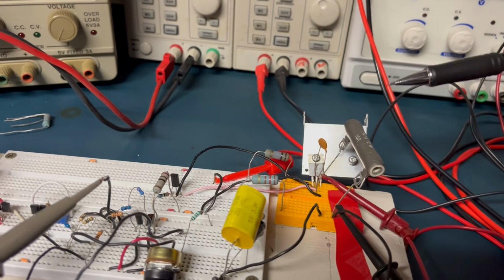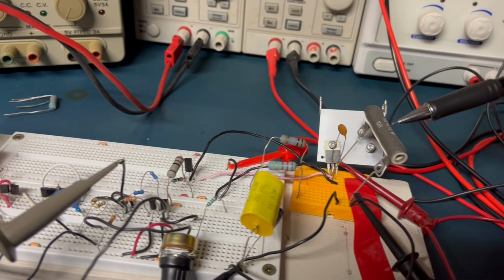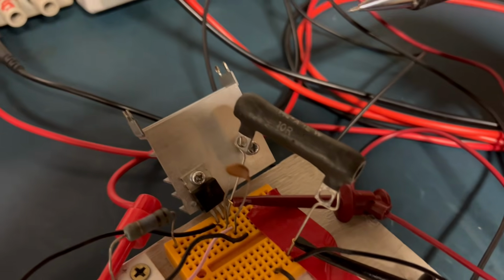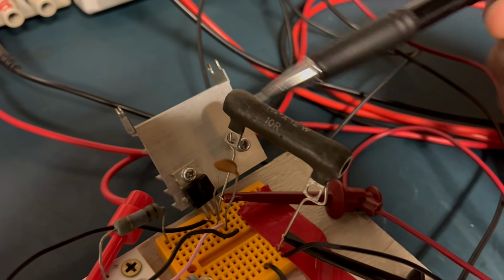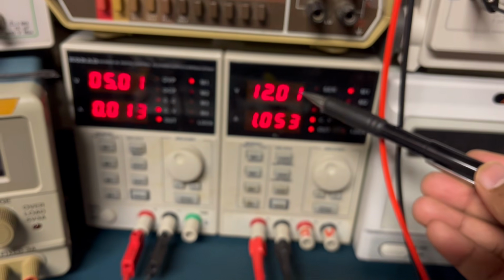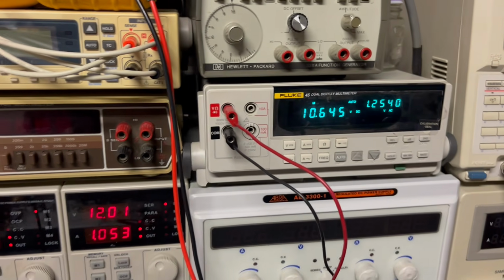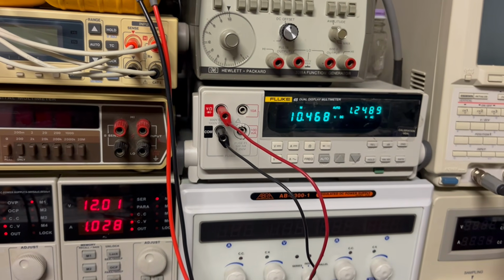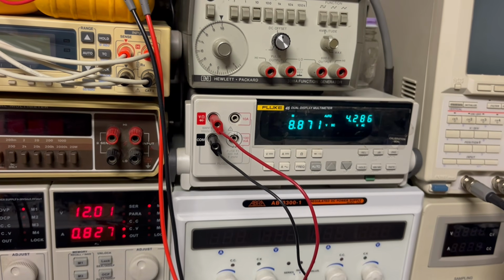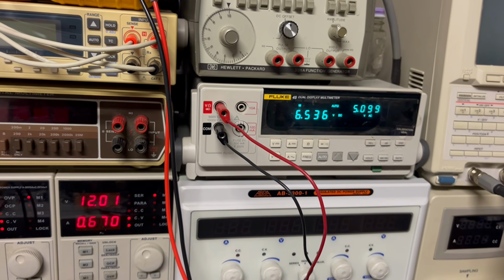Now in this case, I'm not using a motor right now. I'm using a 10 ohm resistor, right? So if you take a look at this, the 10 ohm power resistor is fed from the 12 volts, right? Now this is the average voltage that's coming out of it as the duty cycle is controlled. Look at the average voltage that's across it.